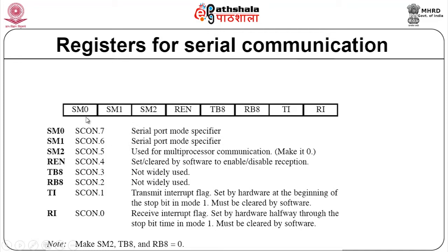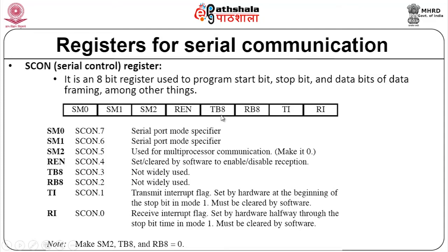Usually we will be setting SM0, SM1 as one, the first mode, which will support UART kind of communication. REN is set so that serial communication is supported. These two flags are set by hardware, and have to be cleared by the software to run things properly. So it is actually the SCON, serial control register.